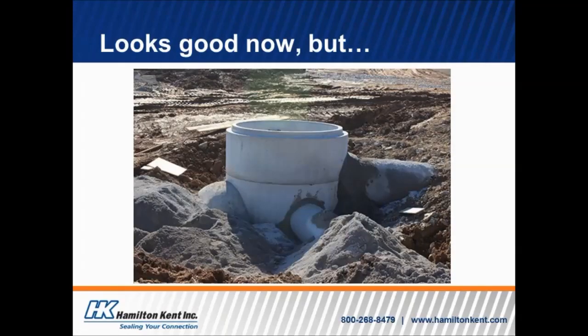This is at a job site I visited not long ago, and this is how they're trying to get around it. They're putting a rather large concrete or mortar shell around that connection with the manhole, and you can see, especially on the left-hand side, there's a pretty big lump where that pipe is, and that's where they've really gone overboard, I think, trying to strengthen that connection.